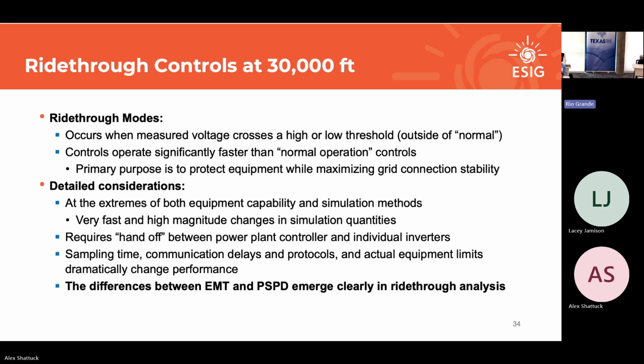There's a lot of misconception about that in the industry, right? I think even at AAA 2000, which I have a leadership role on, we recommended something implicitly about 200 milliseconds, 200, 250. That's wildly fast. And even in ERCOT, right? If you look at ERCOT's model quality test procedures, they may say you have to have your response completed in a second, full response, or 90% of your response in a second. And I think they use the word immediately for the beginning of the response. But what's immediate mean? Is immediate 200 milliseconds? Is immediate 500 milliseconds, a half a second?